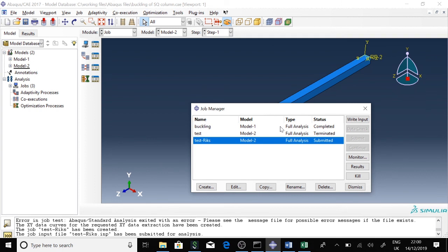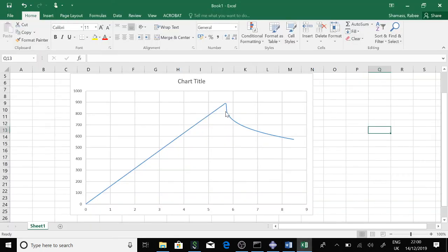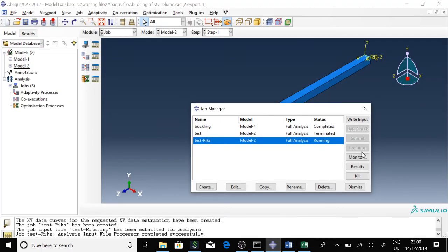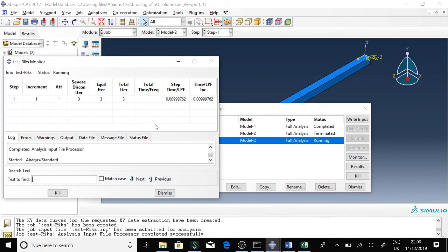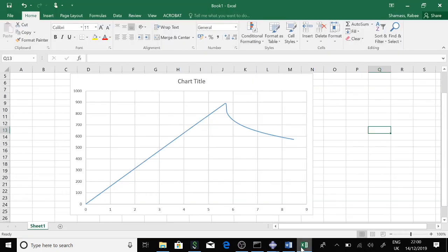Now in this case actually this works because it doesn't go back and then buckle. Basically we can still use a displacement with general static. My advice to you is, if it doesn't, you can directly work it out using the Riks method if you want to continue. So this Riks method will generate the whole nonlinear analysis. It goes up linear and then buckles. For this case it is working without the Riks method.